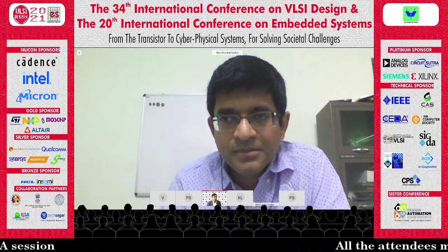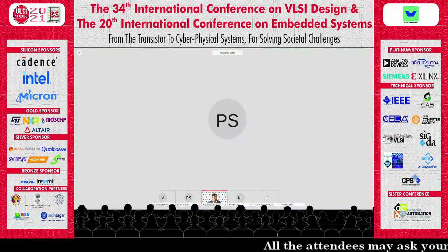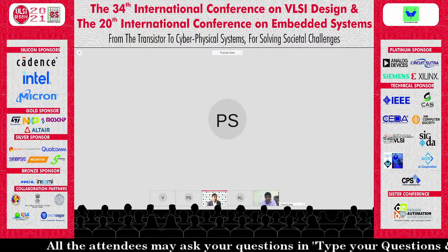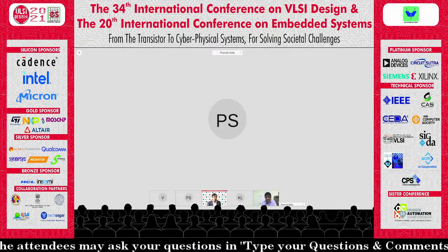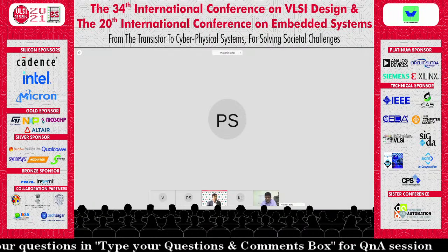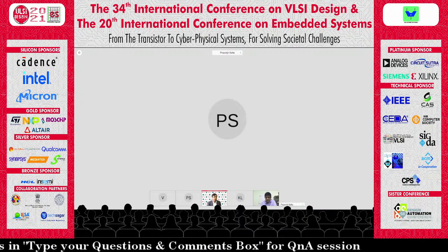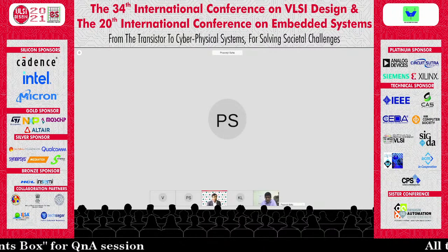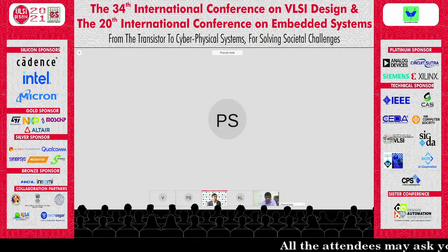Yeah, so there is not much difference. But if we look at any parallel stack of transistors, the changes mostly happen if we have a serial stack of transistors. Generally, what we see is that the transistor that is the most sensitive, for example, let us consider the normal Elmore delay model: the transistors whose resistance value is present the maximum number of times get sized up, so they will have a lower resistance compared to the other transistors.